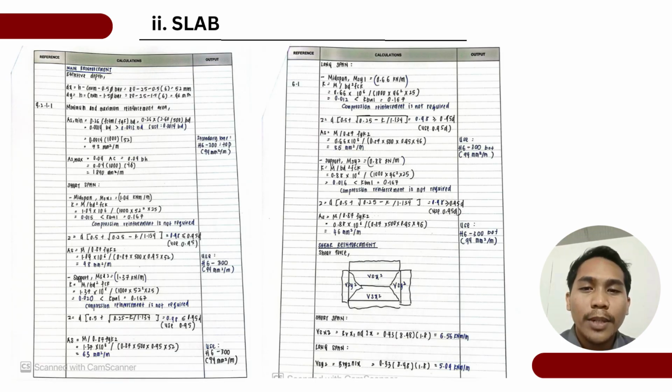For the reinforcement design, the effective depth for X is 52 mm and for Y is 46 mm. Reinforcement selection: while the required steel area is relatively low, we have provided H6 at 300 reinforcement throughout the panel for efficiency.